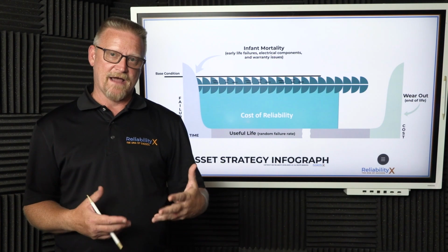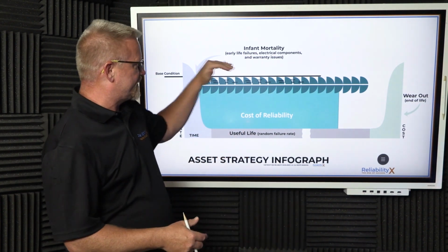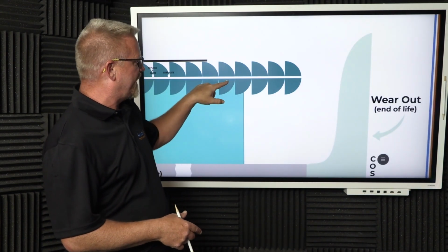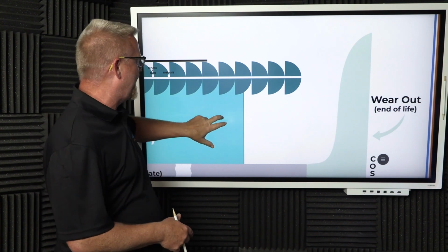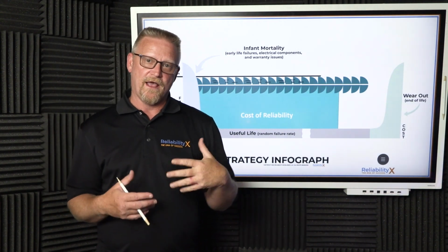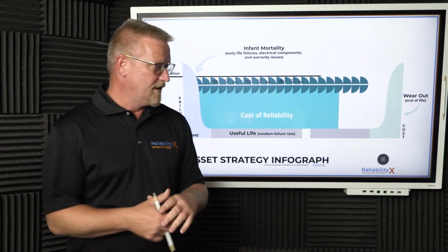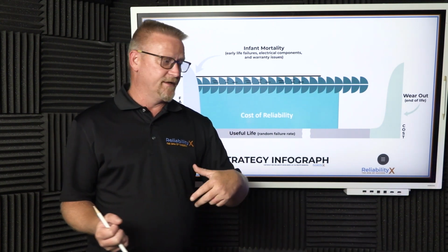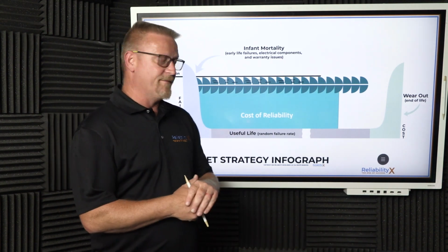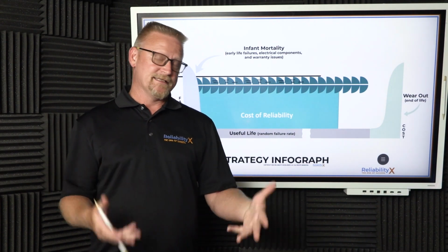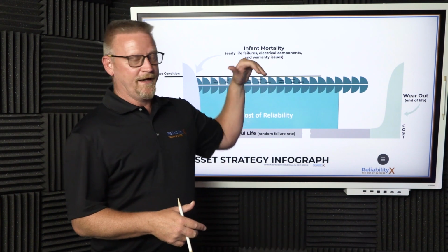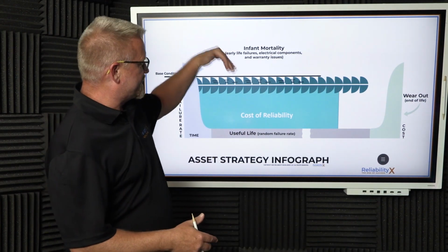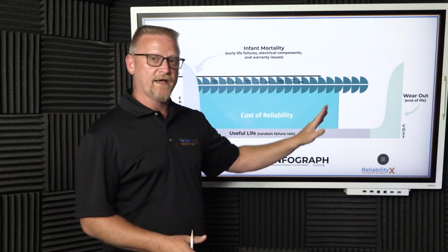The cost of that reliability is the inverse of that sawtooth pattern. And so as we deteriorate, the cost to operate goes up. And as we restore to base condition, it comes back down. So we deteriorate and cost more. For example, as our impeller wears, our energy use goes up. In order for the pump to operate within its parameters, we have to ramp up the VFD as the impeller wears, and so it costs us more. And then if we replace the impeller, we get back down to base operating cost. And so the opposite of the maintenance pattern is the cost of reliability.